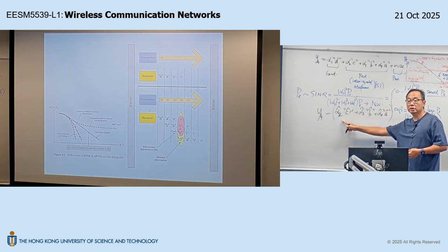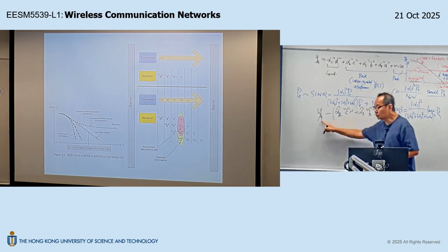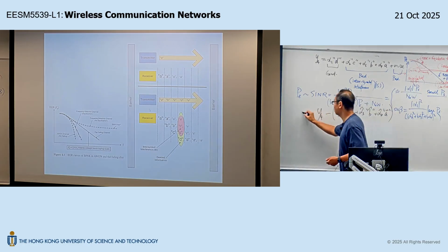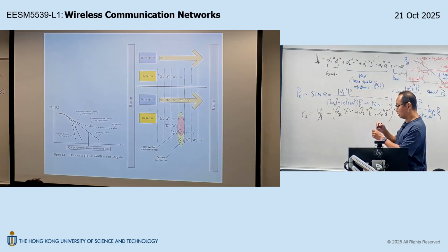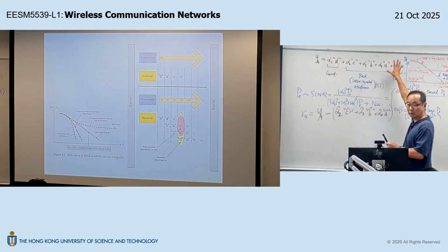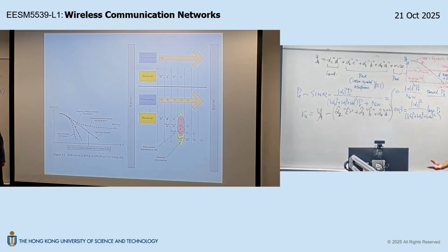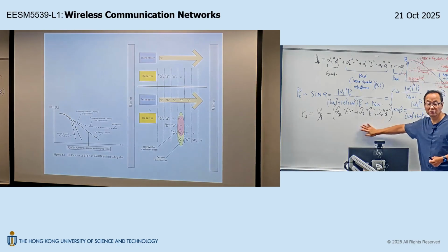These are the regenerated ISI. If you subtract this, I call the result R4. This R4 will contain just the good term and the noise only, right? And in this case, when you demodulate based on R4, your performance will be the same as the flat fading case, the blue curve, if you can do perfect cancellation, okay?